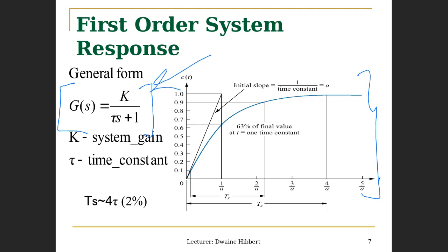Note that the highest power in the polynomial is of order 1, s to the 1. So you can recognize a first order system by looking at the polynomial in the denominator. We'll speak a little more about that very special polynomial, but for now bear in mind that this is the structure of all first order systems, with a system gain K and a time constant tau respectively.